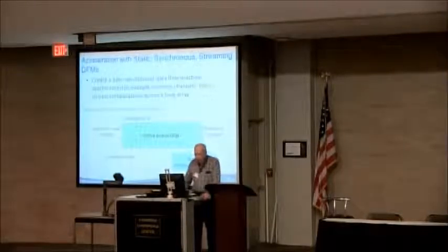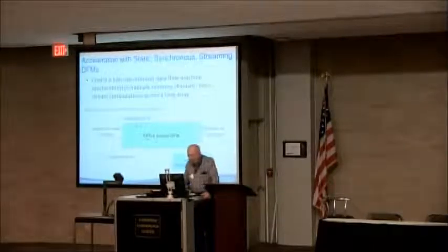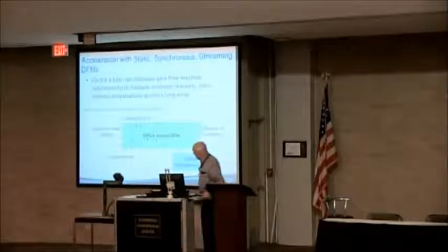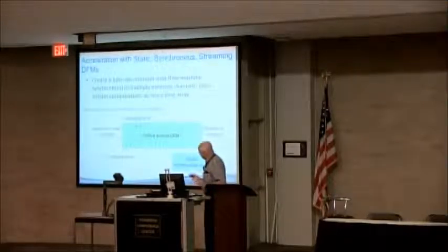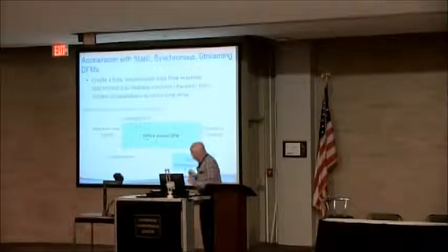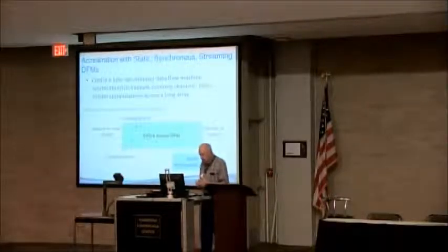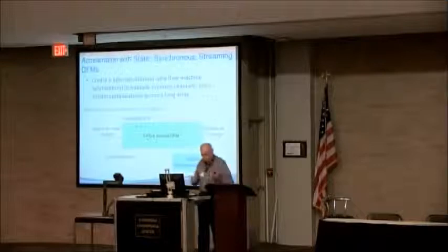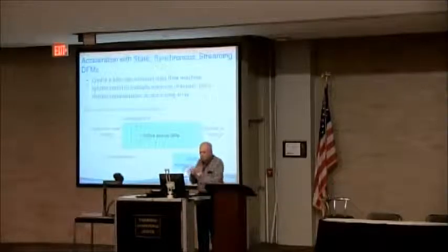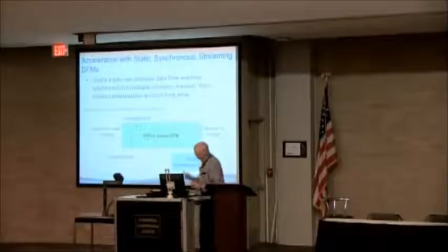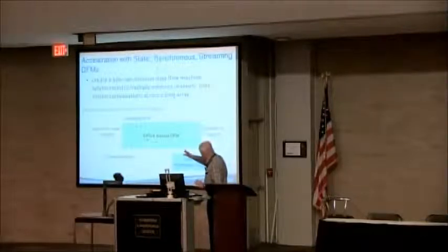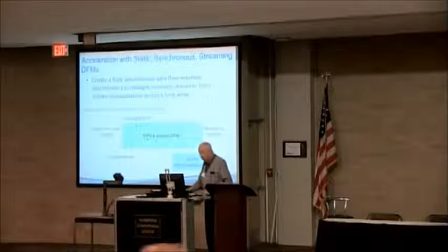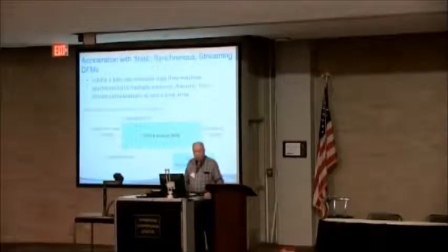So, this is a graphic of what I just said. Data comes in from the host memory. Remember now, the computation already has been written for the host. We take out the compute-intensive portion, put it in a data flow machine, put that in the FPGA, and then create this long data flow machine pipeline. This pipeline is frequently 3,000 or 4,000 stages deep.